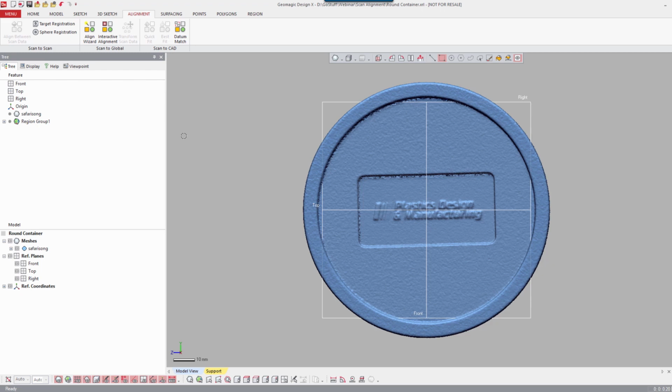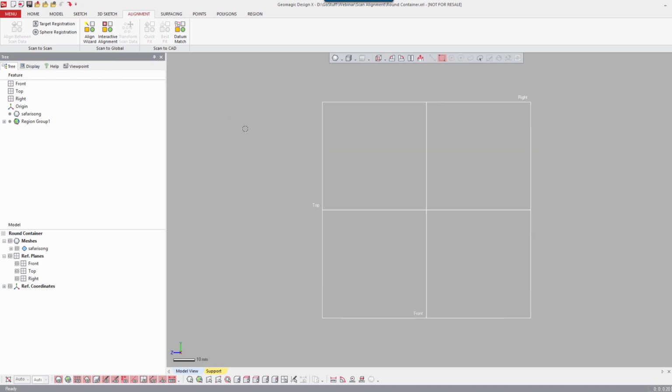You could do another one right on the top of this. So you could sketch right on this plane like I said, draw a couple of lines and then use those to line up your X and your Y instead of what we have now. Again, I'm on the YZ, and normally on this I like the X and the Y coming through the middle there. So I would have a little bit more work on that, but at least with a couple of seconds' worth, particularly on a round, that Align Wizard just does wonders for you. Not much effort at all. So I'm going to undo all that here if I can get him off in space again.